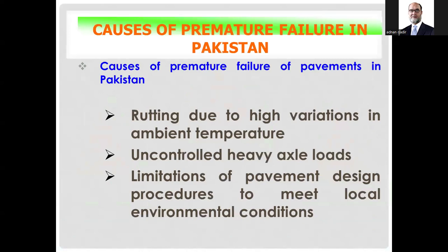Now, what are the pavement problems? We have discussed it. We all know that in Pakistan there is rutting because of the high temperature. Even if you can control the load, the temperature is higher. If you go to upper Sindh, like Nawabshah, maybe Tharparkar or Jacobabad, you have higher temperatures.